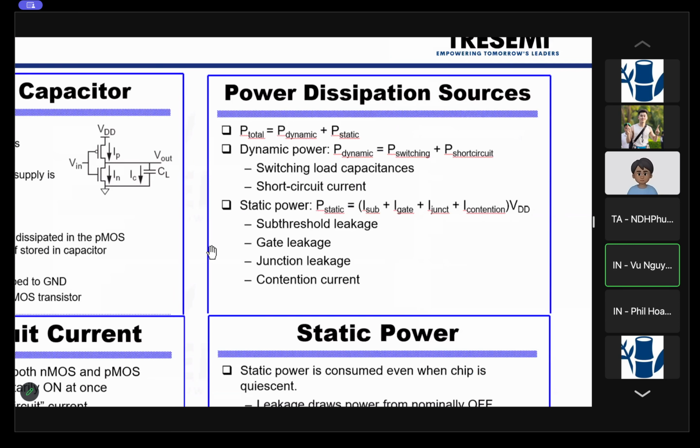So when we design, we have to take that into account, especially for chips that target automotive or industrial, which have to work at like 125 C junction temperature. The leakage current is very high. So make sure that our circuits and our power grid account for the power voltage at a high temperature. Yeah, very good point.